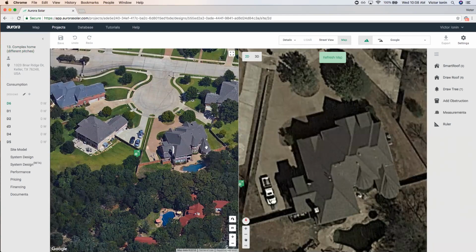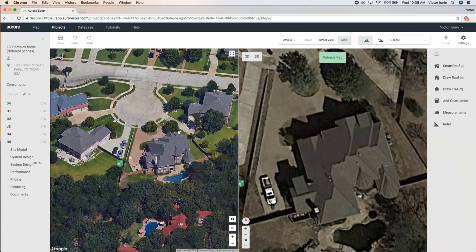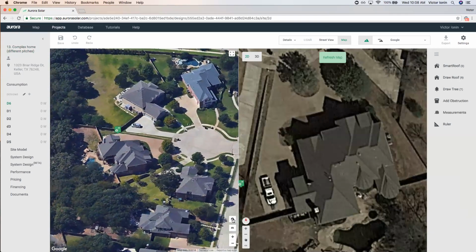I notice that there's a lower level here that's kind of separate from this upper level. Let's draw that separately, right? You notice that I can change the heights of two different structures. So I can make this piece 1 story tall, make the other larger piece 2 stories tall. So let's ignore this bottom piece. As you swivel around, you'll notice there are shed dormers. Let's ignore that. We can use the shed dormer tool to draw it in afterwards.